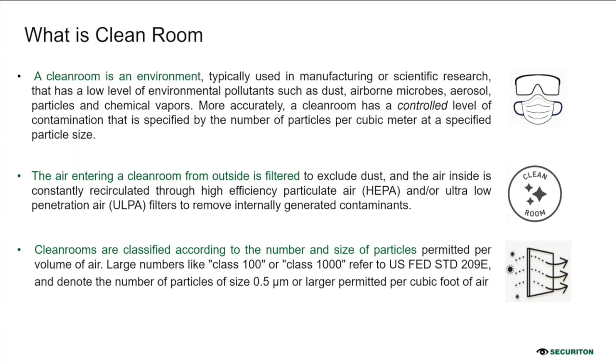So the clean rooms will be classified according to certain standards, which formerly was known as FED standard 209E, but is now superseded by the ISO standard, which I'll be explaining on the next slide. A clean room is a room where you have clean air to do work, because IC manufacturing or fabrication needs a very low dust level or zero tolerance of dust.